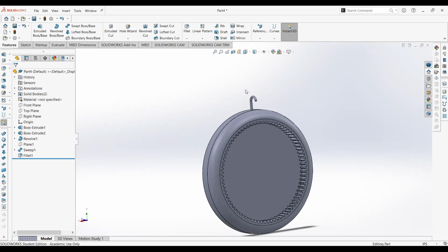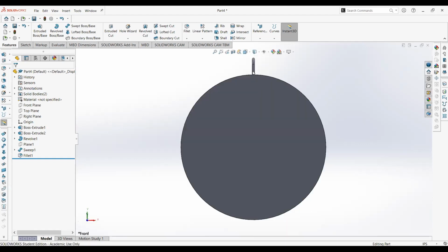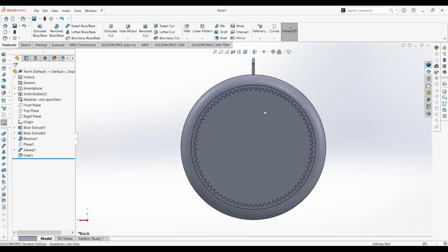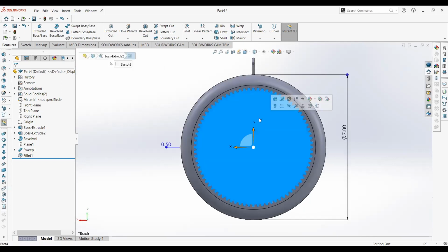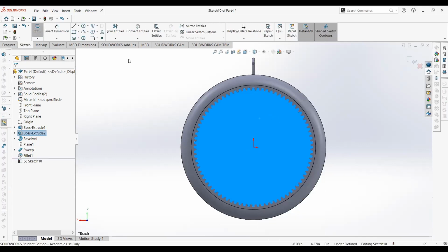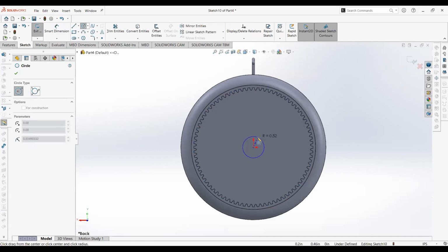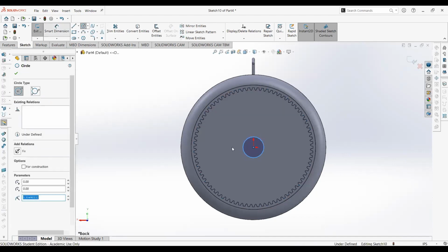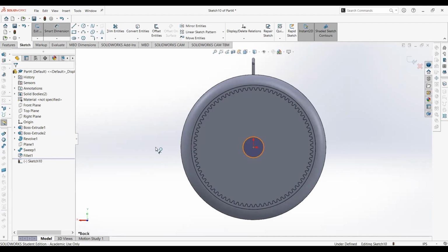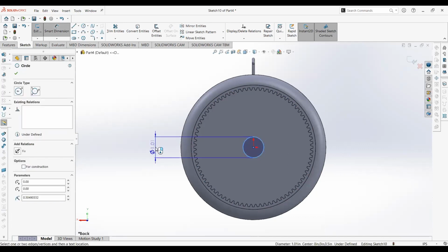All right, did everyone get the fillet? Because we've got like 5 minutes left, I'm going to move on. Go to front or back view, I guess in this case. You're going to hit this back panel, sketch, which is what we've done before. And then just another circle from the center, from the origin. You're going to dimension this. This is going to be 0.325.